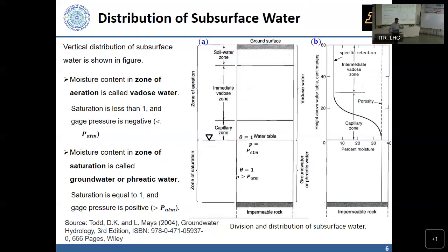And therefore some of these definitions are used loosely in some sense. In many groundwater studies, if we are thinking of an unconfined aquifer, it's not uncommon to think of the top of your unconfined aquifer as being at the top of the capillary fringe. So everything that is saturated, we assume to be part of the main aquifer.